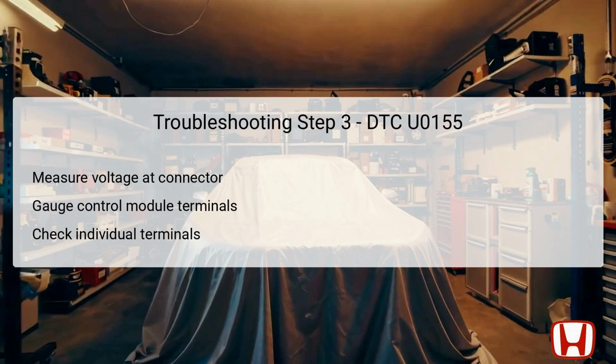If there is adequate voltage supplied, this suggests that the wiring and connections are intact up to that point. Conversely, if voltage is not present, it indicates an interruption in the electrical circuit, necessitating further troubleshooting to identify and resolve the specific issue affecting voltage delivery.